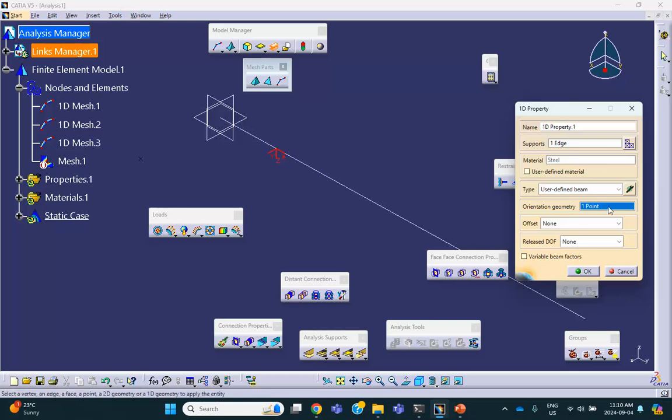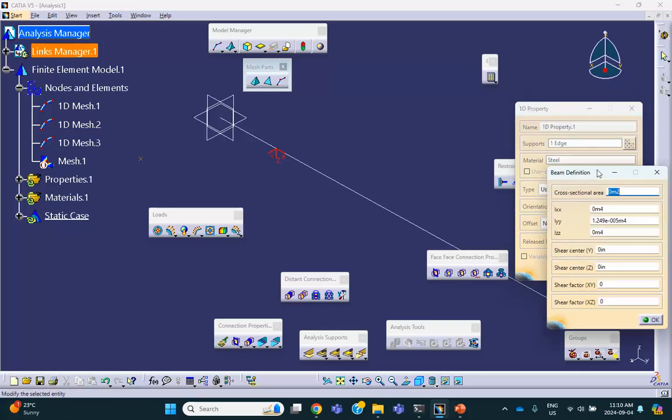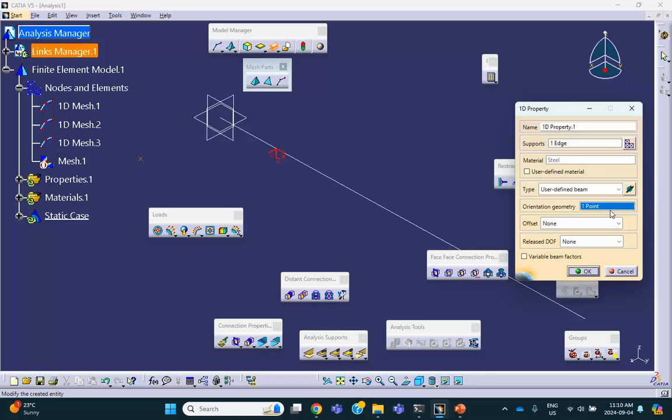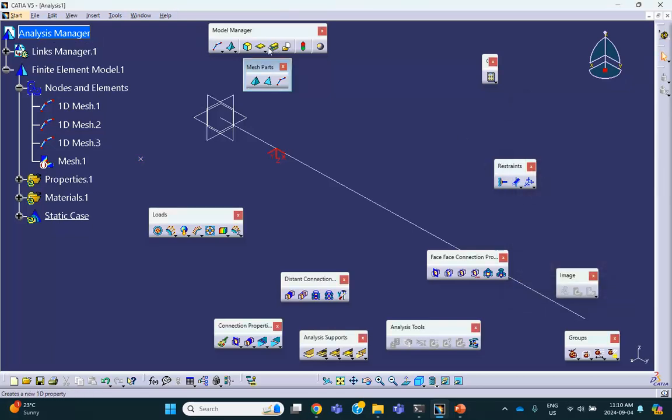Well, that's okay. Now you click on the wrench here, and you know that the cross-sectional area and the bending moment, these x, y, z are referring to the local coordinate system. So the bending direction is y. So I put down 30 inch to the 4. And because my units are set to meter, it converts it into that. Okay. So that's correct. And then say, okay.